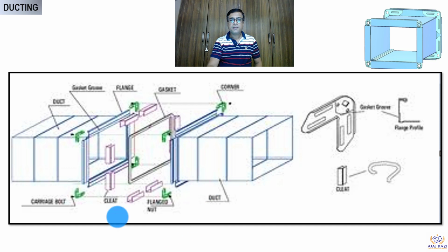Now, as I said, this is the joint reinforcement. This is a joint, and this is where the reinforcement comes. Now, depending on duct size and the standard which you use, this will vary. Generally, now from the factory we get a groove inside the duct so that it becomes a little more stable. Then this is an intermediate reinforcement. Again, based on our charts, we can select what kind of reinforcement is required. As we have seen in the chart, this gives clarity. So I hope it is clear.